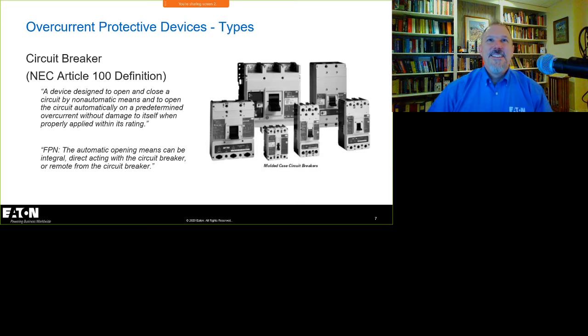Thank you, Ryan. To confirm that software does not calculate arc flash using limiting characteristics. Okay, Hensel, I don't know if that's a question. I'm not looking at the dialogue, but there was a discussion going on YouTube with regard to arc flash. You can use what they call fuse and circuit breaker equations. The fuse equations leverage the current limiting capabilities of the overcurrent protective device. You can turn that on and off in most of the software packages that I've seen.